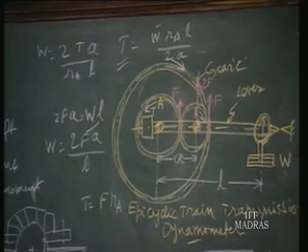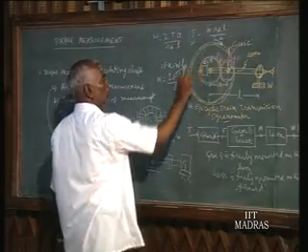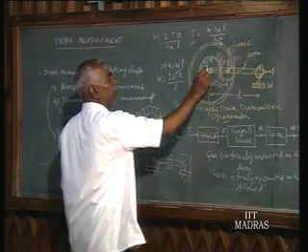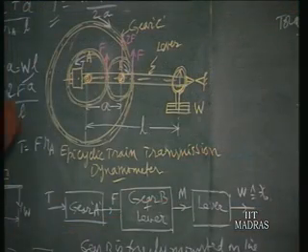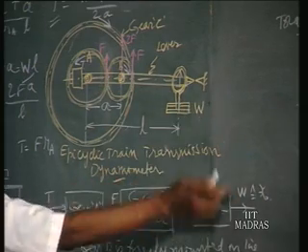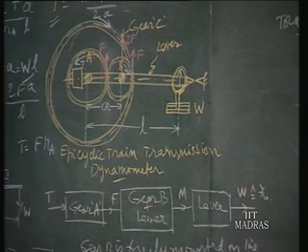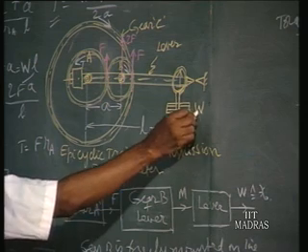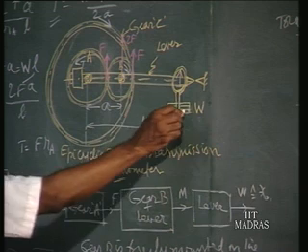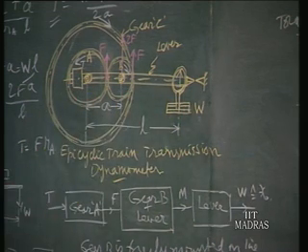That is what is shown here in the signal flow diagram. We have got a torque available that is converted into force F at the pitch line of the gear A. By using gear B and lever, we convert that force into a moment equal to 2F into A, that is being balanced by W into L, that is moment is converted in terms of W force by having the lever. So, as per this equation, W can be calibrated in terms of the weight, different weights can be calibrated in terms of torque. So, by adding different torques here, then you can find the total torque transmitted by this instrument. So, this is one method.